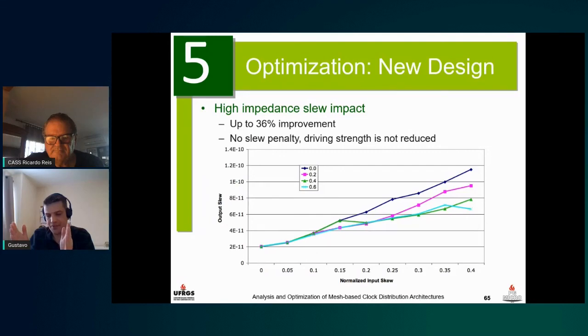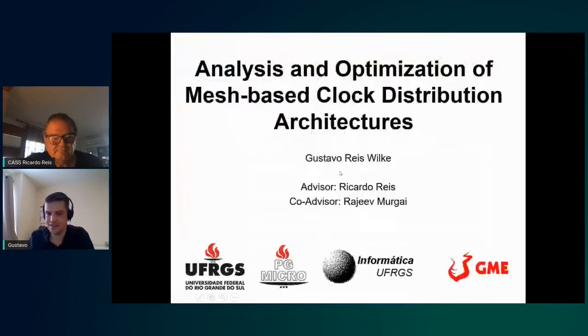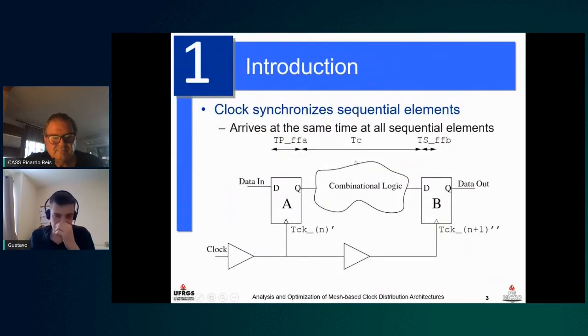If you look at the equation to define the clock period, we need to have time for the data to propagate from the first sequential element to the last one. But the interesting part is that the propagation starts at clock edge n, and then the data is read by clock edge n+1. So we need to directly account for cycle to cycle jitter in the clock period because of that. But as I was saying, the cycle to cycle jitter, from what I remember, used to be very small.